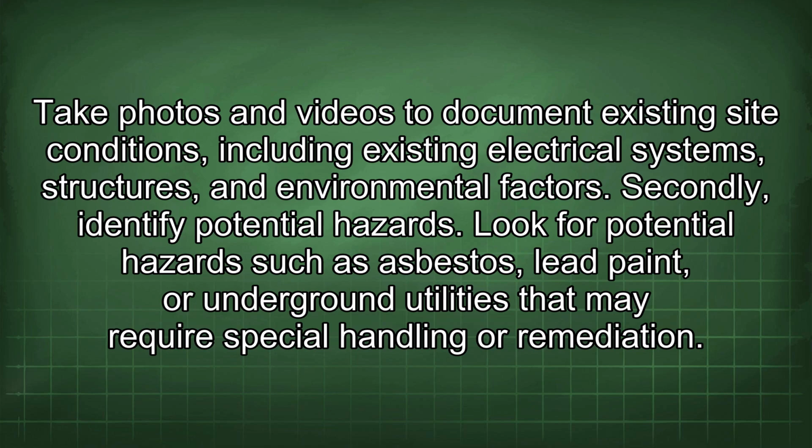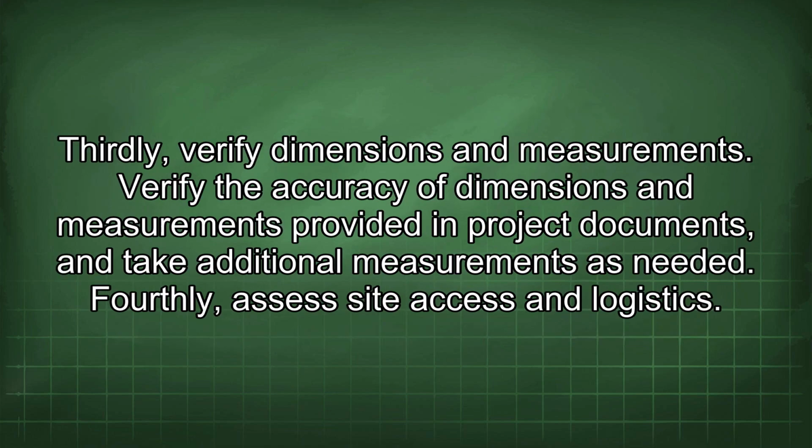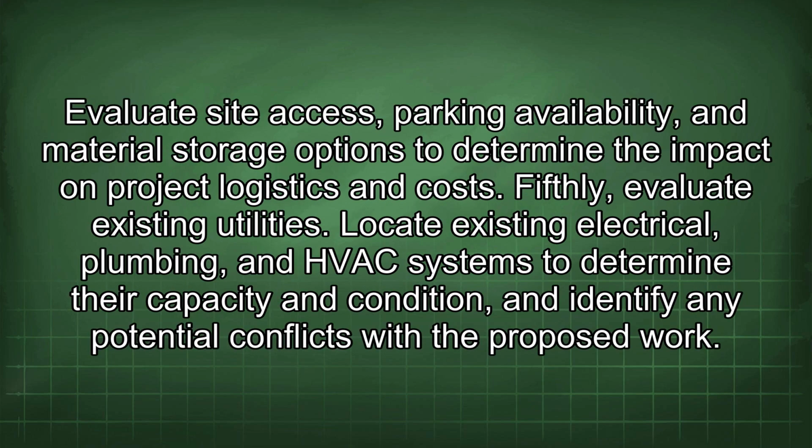Look for potential hazards such as asbestos, lead paint, or underground utilities that may require special handling or remediation. Thirdly, verify dimensions and measurements. Verify the accuracy of dimensions and measurements provided in project documents and take additional measurements as needed. Fourthly, assess site access and logistics. Evaluate site access, parking availability, and material storage options to determine the impact on project logistics and costs.